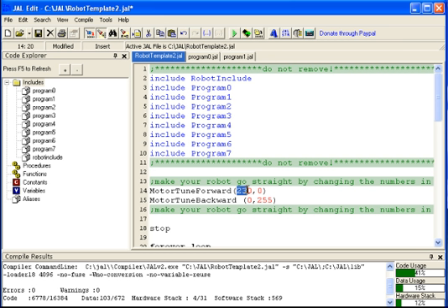Okay, so that's going to slow down motor number 1 in your forward direction to the value of 230 rather than full blast at 255, and hopefully it will closer match your full blast forward of the other motor. So play with these numbers until you get your robot going straight. Get both of the motors turning at the same rate of speed.